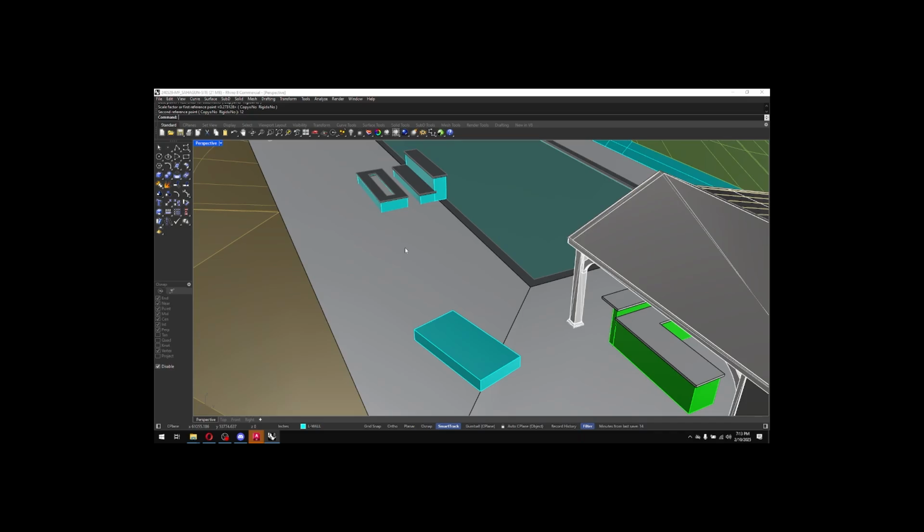Rotate works exactly the same way as it does in AutoCAD. This is the last command. I know I just said that. Rotate3D, you've got to know that one. In this case, think about Rotate3D as a steering wheel. What I need to establish first is the steering wheel column. So what am I rotating around?